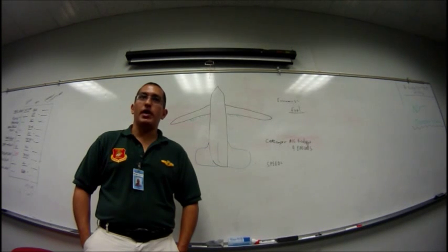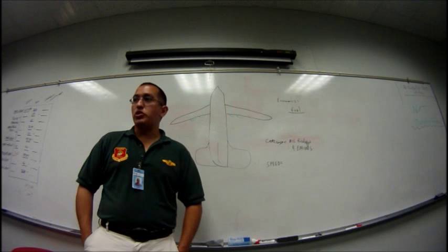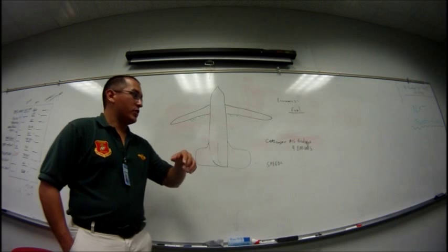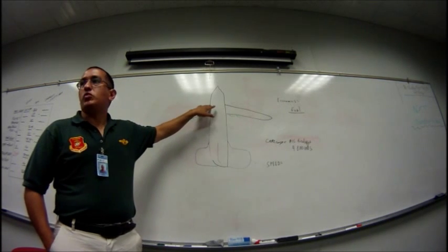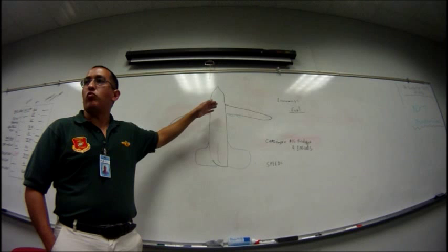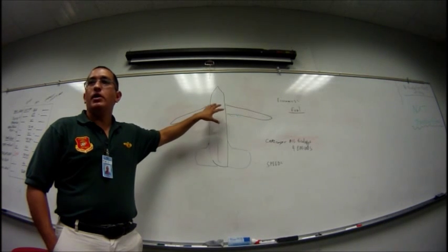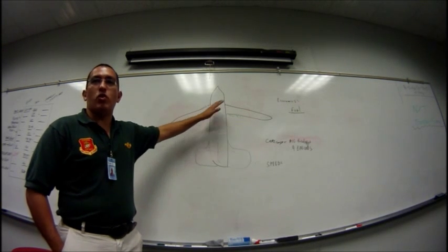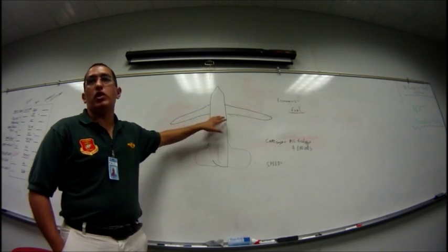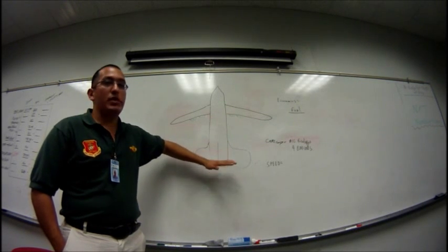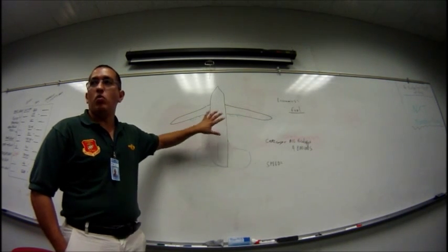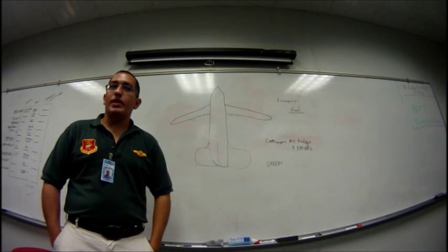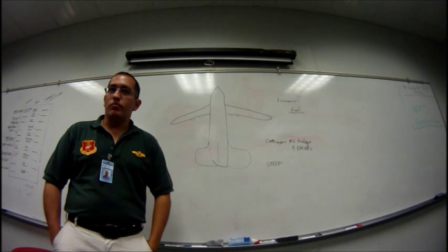So you have the high strength, but you have the weight savings compared to using a weaker metal. Another thing about composite materials is that you can put them together in a seamless design. On a typical aluminum aircraft you'll have seams where the wings meet the fuselage, and rivets, and that all adds up to drag. A lot of aircraft nowadays are coming out with composite materials where it's all one piece, so the wings smoothly blend into the fuselage, and smoothly into the empennage. It's all one eloquent flowing piece of technology, which is great, except when something breaks.